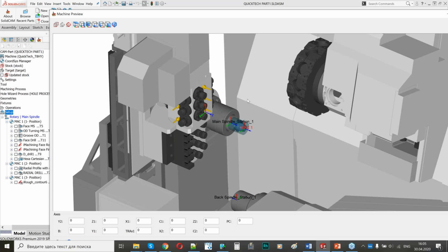After that, I will take my turret and call the tool for the cutoff, tool number 1, I think. Then I will perform the cutoff, and the back spindle should go to its home position in the Z direction, and then it should go to my gantry to perform the operations on the back spindle.